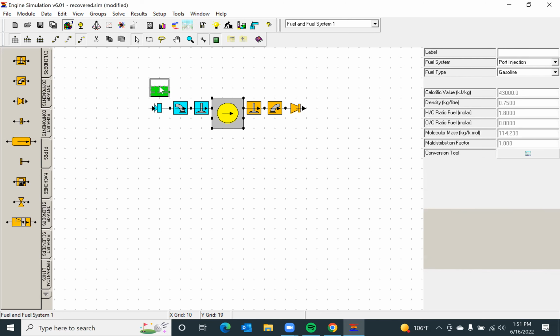And once that is done, you can go to this gas tank symbol that talks about what type of fuel we are using. So in this particular case, you are using gasoline, and then you can have an option whether you are doing carbureted or whether you are doing port injected. By the way, port injected engines are more efficient, carbureted engines are less efficient. So you can have a carbureted engine, you can have a port injection engine. Direct injection and indirect injection are used in diesel engines.